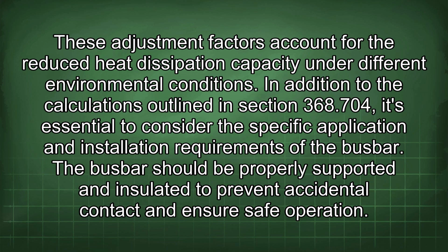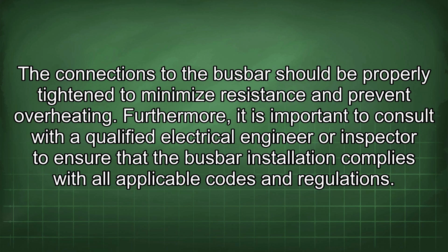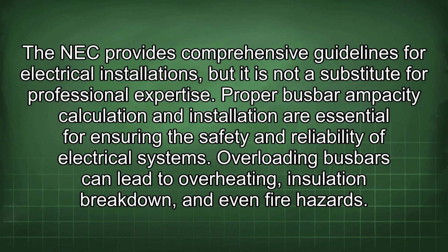The busbar should be properly supported and insulated to prevent accidental contact and ensure safe operation. The connections to the busbar should be properly tightened to minimize resistance and prevent overheating. Furthermore, it is important to consult with a qualified electrical engineer or inspector to ensure that the busbar installation complies with all applicable codes and regulations. The NEC provides comprehensive guidelines for electrical installations, but it is not a substitute for professional expertise. Proper busbar ampacity calculation and installation are essential for ensuring the safety and reliability of electrical systems.